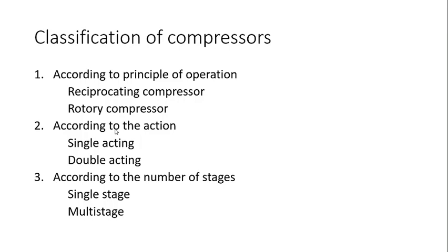According to the action, there is single acting reciprocating compressor, and double acting compressor is also there. And according to the number of stages, single stage compressor and multi-stage compressor. In single stage, the air is pressurized in one stage, but in multi-stage we have more than one stage in a single machine to increase the pressure of the flowing fluid.